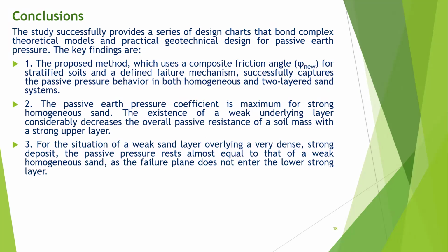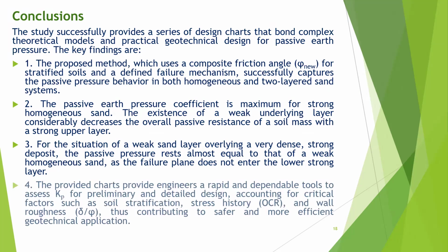For the situation of a weak sand layer overlaying a very dense, strong deposit, the passive pressure is almost equal to that of a weak homogeneous sand, as the failure plane does not enter the lower strong layer. Fourth, the provided charts provide engineers rapid and dependable tools to assess K-passive, or passive earth pressure coefficient, for preliminary and detailed design, accounting for critical factors such as soil stratification, stress history, that's the OCR, and wall roughness, delta over phi, thus contributing to safer and more efficient geotechnical